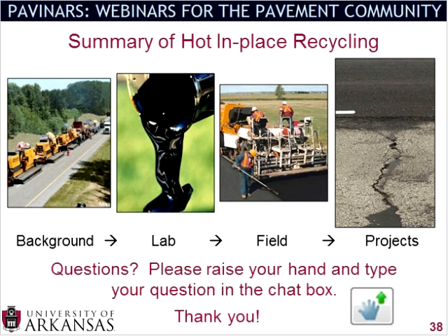Now, if you feel that it may be a little dry, that may be an opportunity for slurry seal or microsurfacing if you want to keep the asphalt content a little lower in the surface itself. So I do apologize, Daniel, but there really are no right or wrong answers. I think there are just a lot of options. So if you're considering going this route, I would recommend contacting some states in your area or some contractors around you, see if they have used it, see what their experience has been, because it's not only material dependent, but it's also climate dependent. But thank you for that question.